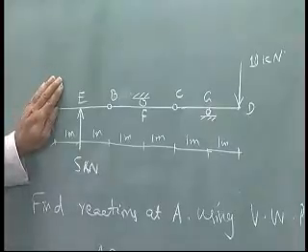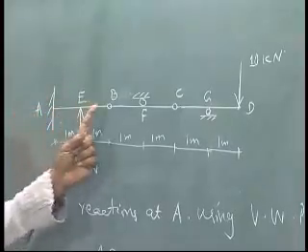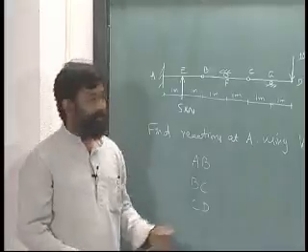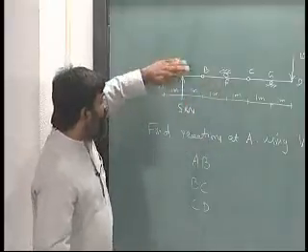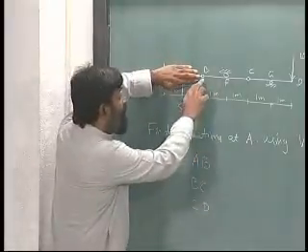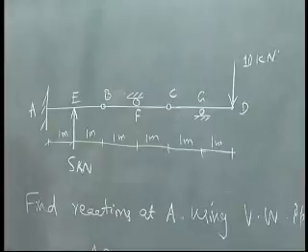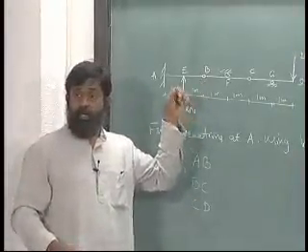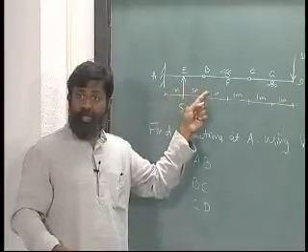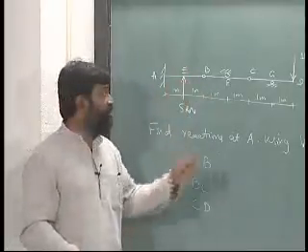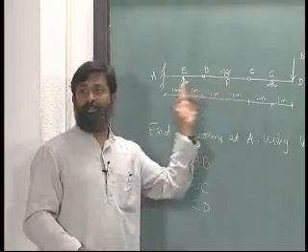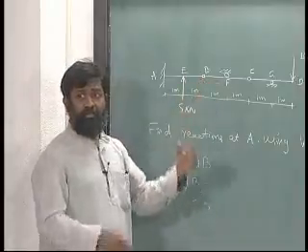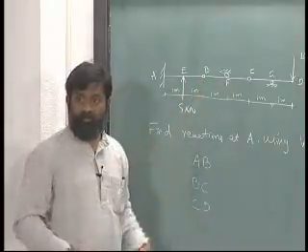Let us come back to this A later. Between AB and BC, what do I know? Supposing I fix AB, the displacement B of BC is fixed, alright. So it offers a constraint at B, whatever is the displacement of AB at B, it is the same displacement of B at BC, correct, and therefore can it rotate between them? The rotation between them is allowed, right.